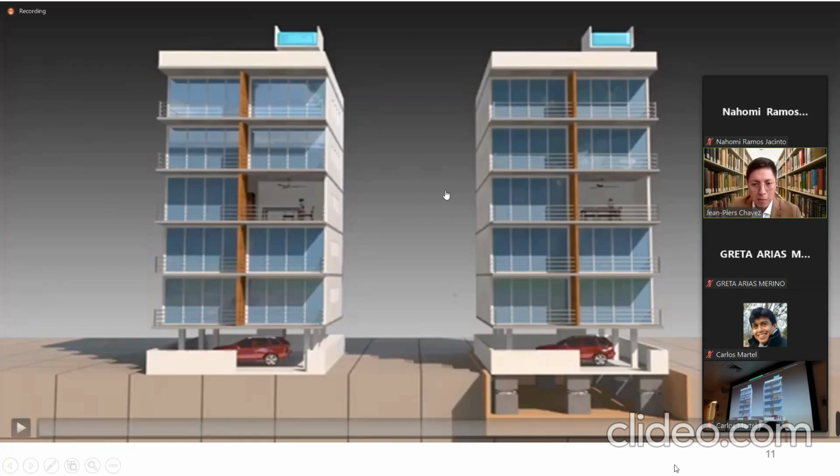The building on the right has the seismic isolation interface, but in contrast, the building on the left doesn't have any seismic protection system. When the earthquake starts, you can see the first damage in the structural elements, columns, beams, and so on, and then you can see the damage inside the building. Why? Because the floor acceleration increases in each story.